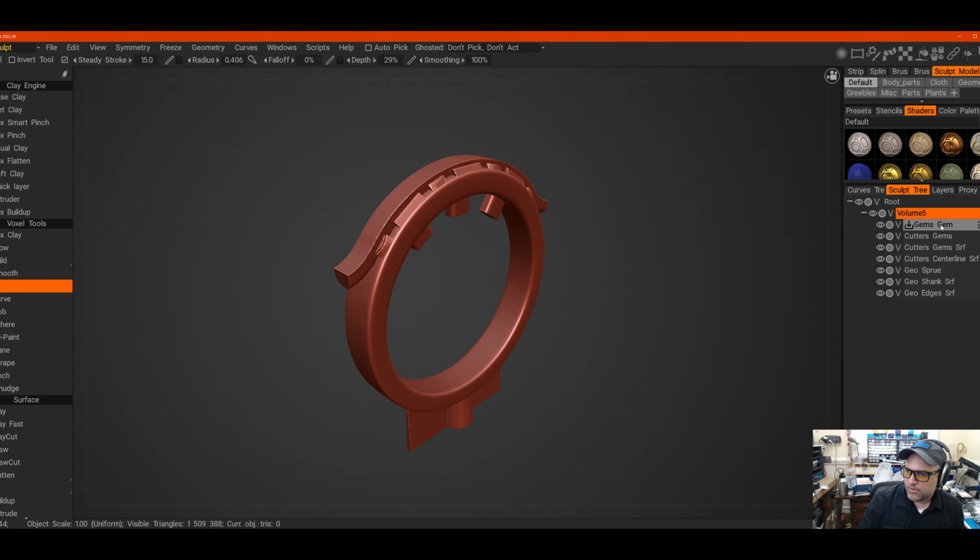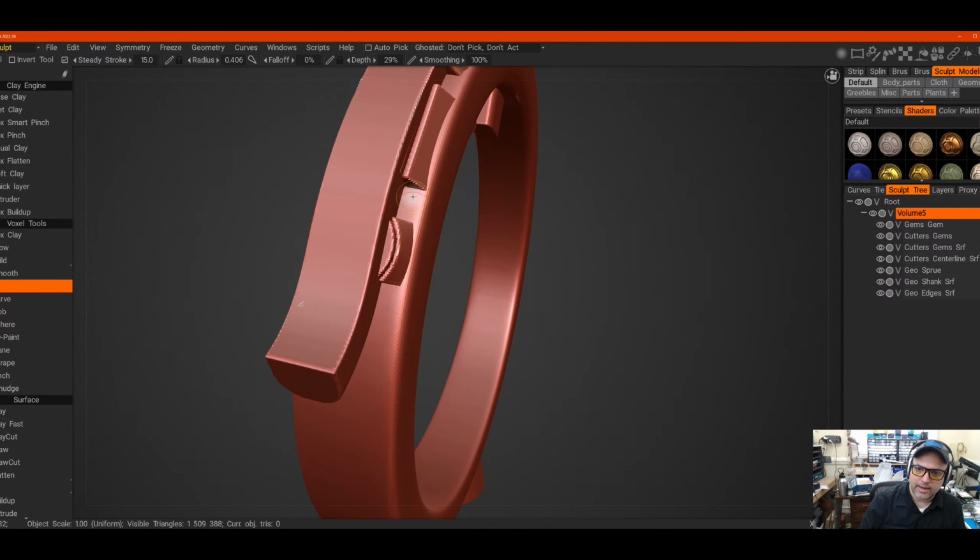Okay, so over here we have cutters, cutters, cutters. These are going to be Boolean subtract. We have geo, geo, geo. These are going to be Boolean union. Sometimes you can just say join all of these together, join all of these together, and cut this from this. Other times you may want to do it in 2 stages. A lot of times I will go quick in Rhino and have a cutter that would completely decimate a feature next to it. I'll just have that cutter cut that piece before I join those 2 positive pieces together.